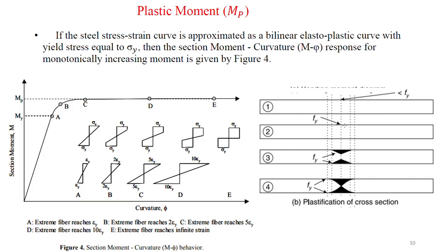The structure will regain its original shape and size. You can see at the point sigma y itself, it will regain its original shape and size. But in case 3, you can see small deformations have started after the yield limit. After it has crossed this yield limit, we can slowly see the deformations of this particular beam. You can see here the necking portion of this beam when you apply the flexural load. Here dimensions have changed, the thickness of this material has changed.